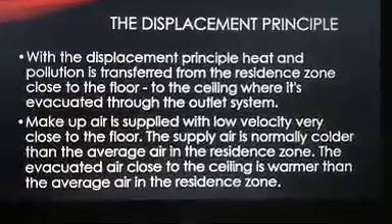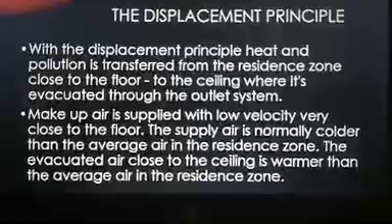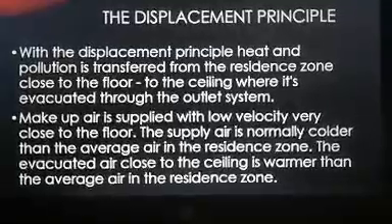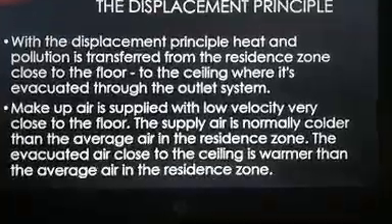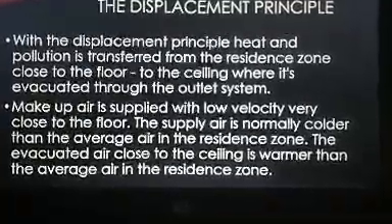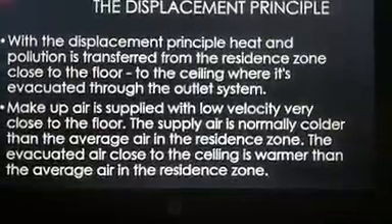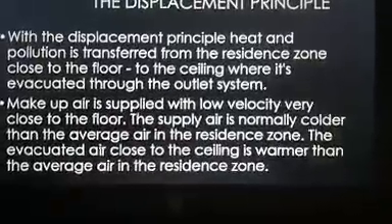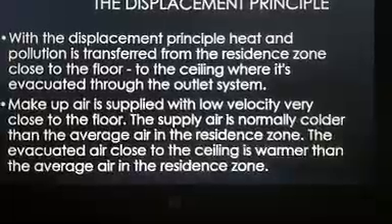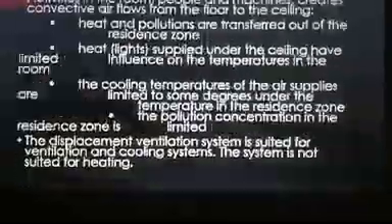The displacement principle. With the displacement principle, heat and pollution is transferred from the resident zone close to the floor to the ceiling where it's evacuated through the outlet system. Make-up air is supplied with low velocity very close to the floor. The supply air is normally colder than the average air in the residence zone. The evacuated air close to the ceiling is warmer than the average air in the residence zone.